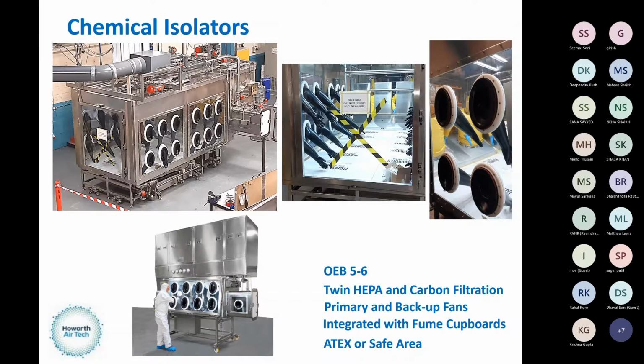And with this particular example, because of the chemicals that were being handled or potentially being handled, we had HEPA filtration as well as carbon filtration, including some backup systems, so backup fans, just because the customer needed that high level of protection should a fan fail or should a filter get blocked. We've got basically a safety system within a safety system here. So again, very bespoke and designed specifically for the application.